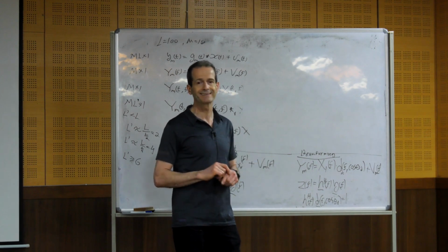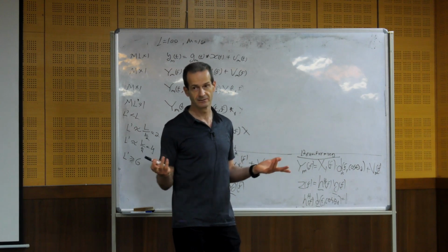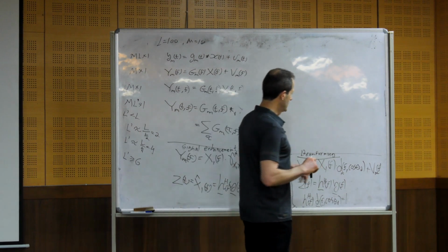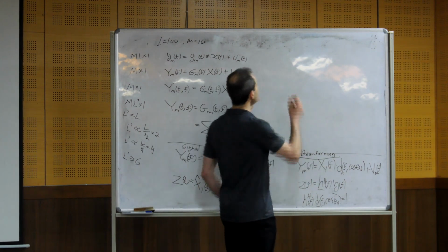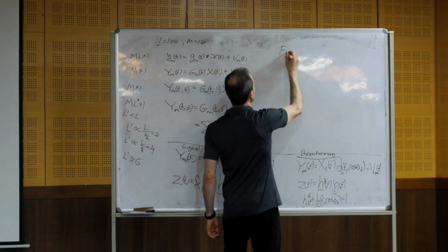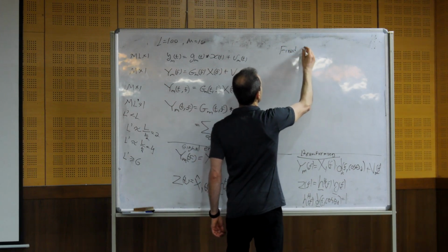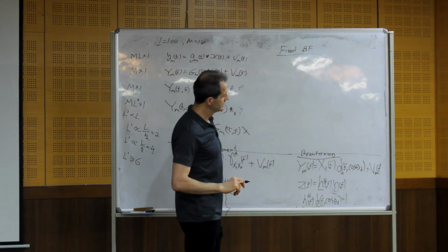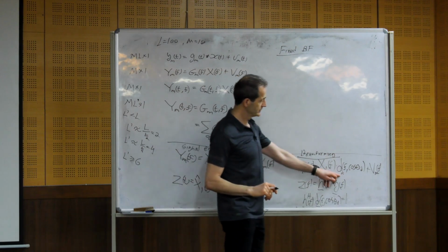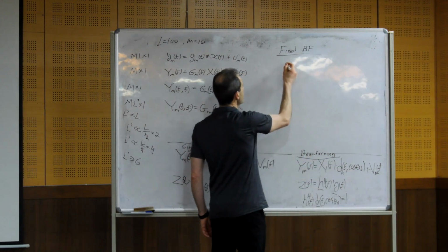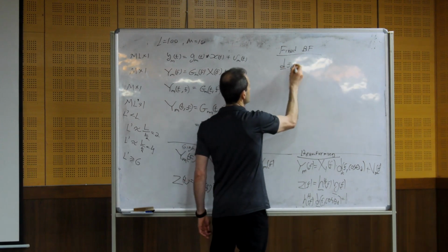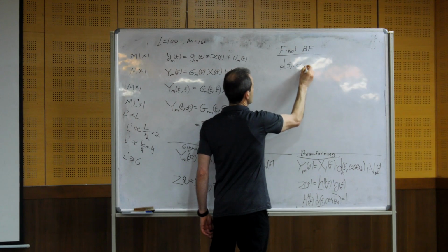So I don't work with these correlation matrices of the noise and the desired source. With fixed beamforming, what I use is theta d, okay? Also I use the steering vector for each frequency, theta d.